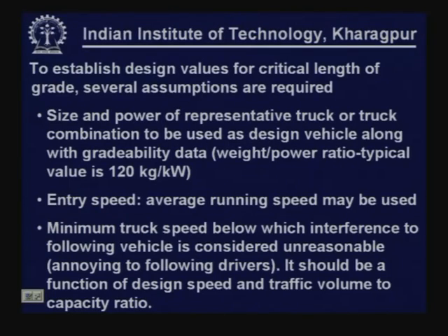Then it is also necessary to define the entry speed, which may be taken as the average running speed on plains. Then the minimum truck speed below which interference to following vehicles is considered unreasonable or annoying to the following driver.